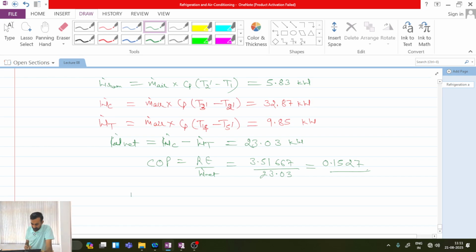So as per ideal gas equation, PV is equal to MRT. If I have to write this ideal gas equation in rate form, then how can I write? PV dot, where V dot represents the volumetric flow rate, and on the right hand side, in place of mass, I have to write mass flow rate, m dot into RT. So I can simply apply this equation.